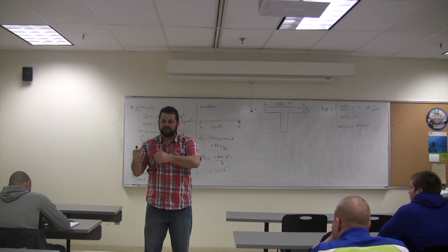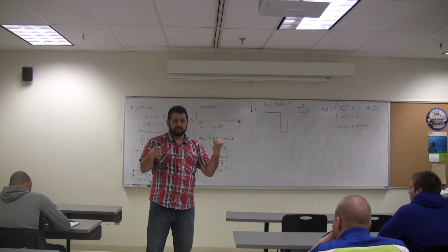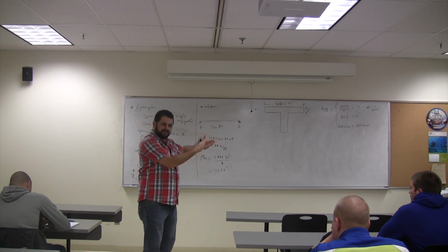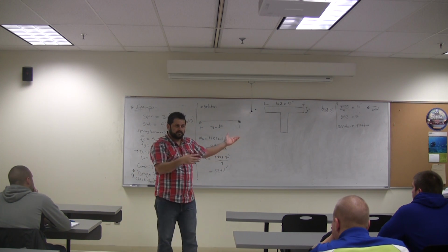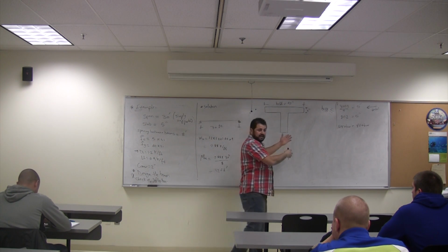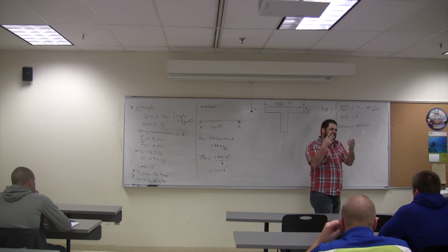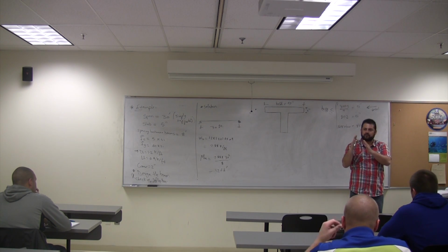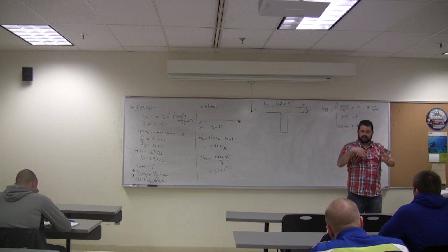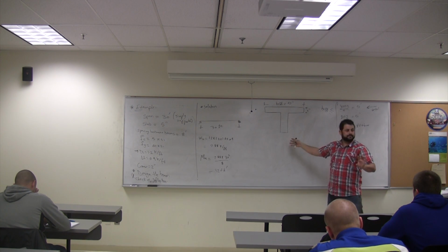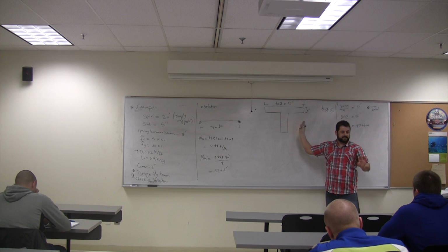If all will not be enough, we went with doubling. But if we think it will be enough and the T-beam is a strong beam, I may go with half of that number, or 0.6 of that number, any number I want, as long as I am less than rho 0.005. If I use that rho, then I can calculate B web and D, right?